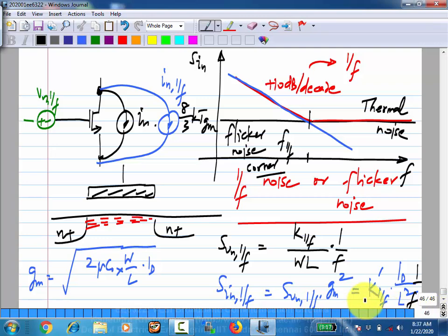So this is about the circuit models. In summary, by the way, if you find cases where the resistors have significant flicker noise, all you have to do is add another spectral density term that's proportional to 1 by f. That constant will be given by the process manual. Similarly for bipolar transistors. It just turns out that in a bipolar transistor also there is flicker noise, but the flicker noise corner frequency is usually much lower. So it is not as significant as in a MOS transistor.